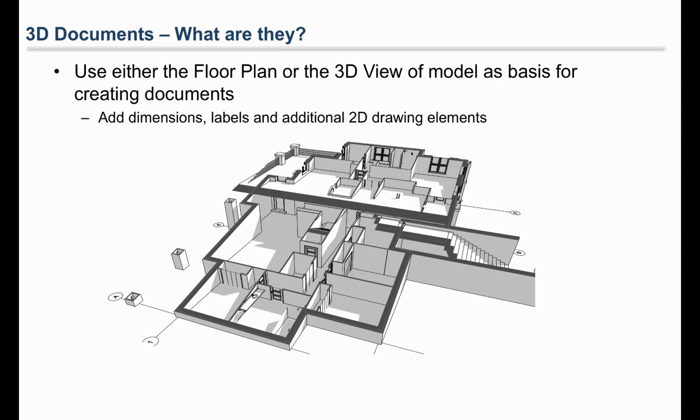A key thing to note here is that the 3D document is live to the model and revisions stay current. Because it's not possible to add dimensions and annotations to the 3D window, I try to push using 3D documents as the source of your details so you don't end up with redundancy in your drafting. It's frustrating to put so much effort into the model and then end up converting it all to 2D details.